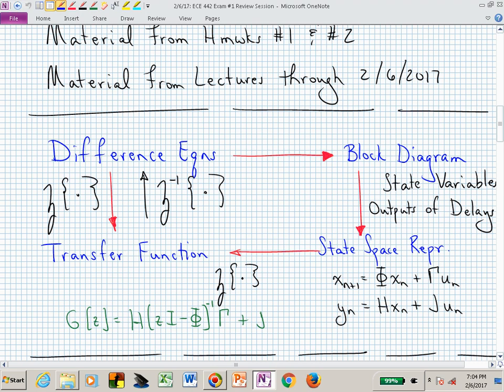You should be able to inverse Z transform these expressions that are Z to the minus 1 times capital Y of Z, Z to the minus 2 capital Y of Z. That's just going to be little y of n minus 1, little y of n minus 2. That will give you a difference equation. So let me change that. I am rethinking my statement: if I give you a transfer function, I may not ask you to find the time domain waveform. That requires the region of convergence. But going back to a difference equation, you should be able to do from a transfer function.